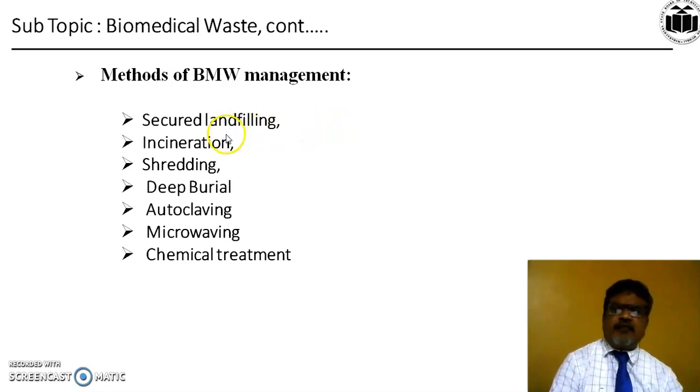Now there are various methods for management of biomedical waste. First is secured landfilling, then incineration, then shredding, then deep burial, then autoclaving, then microwaving and then chemical treatment. So secured landfilling is similar to sanitary landfilling. Only difference is that in secured landfilling, two liners are used.